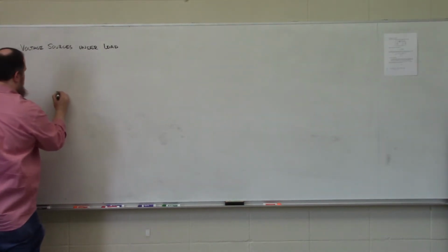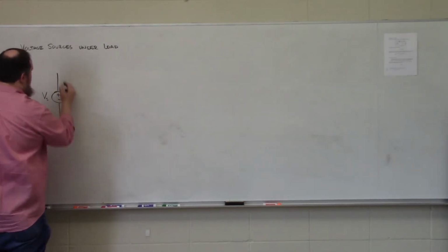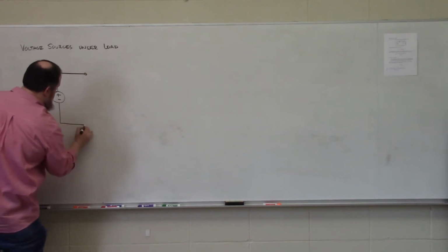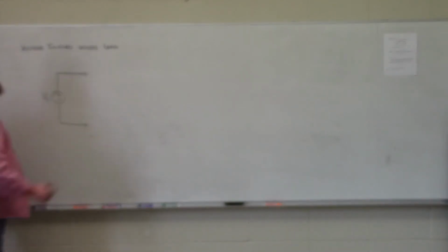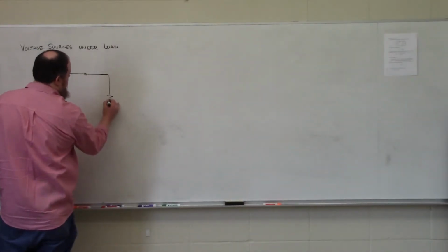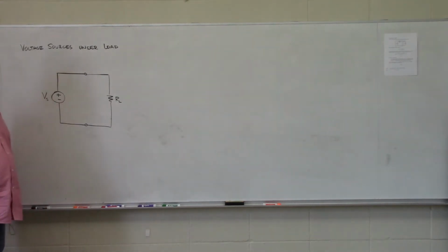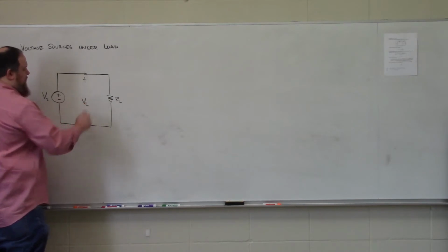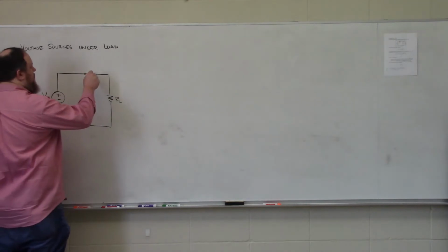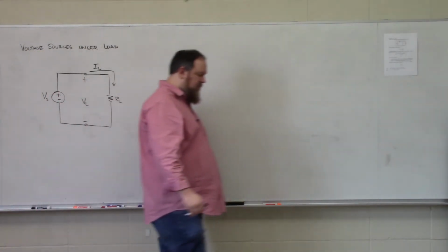So let's say that we have a voltage source Vs, and it's an independent voltage source, so we know that the difference in electric potential between this terminal and this terminal is exactly Vs, and we connect it to what I'm going to call a load resistance RL, where we will observe some voltage drop VL over our load and some current IL flowing through our load.